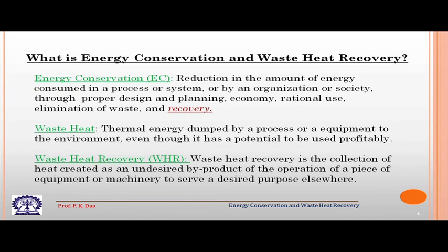So, this is a mandate that a certain amount of thermal energy has to be dumped to the environment. Now, while this dumping is essential, how much of it and at what temperature we are dumping the thermal energy, that is a concern. But whatever may be the quantity or temperature at which we are dumping the thermal energy, this energy is called waste heat. Now, what is waste heat recovery? Waste heat recovery is the collection of heat created as an undesired byproduct of the operation of a piece of equipment or machinery to serve a desired purpose elsewhere.